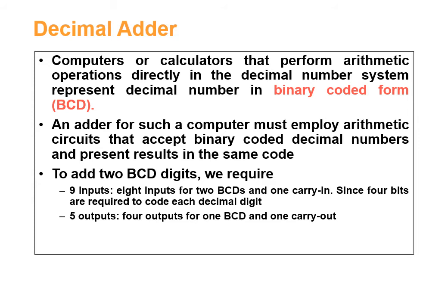If V is equal to 0 after an addition or subtraction, then no overflow occurs and the n-bit result is correct. If V is equal to 1, then the result of the operation contains n plus 1 bits, but only the rightmost n bits of the number fit in the space available. So an overflow has occurred. The n plus 1 bit is the actual sign and has been shifted out of position.